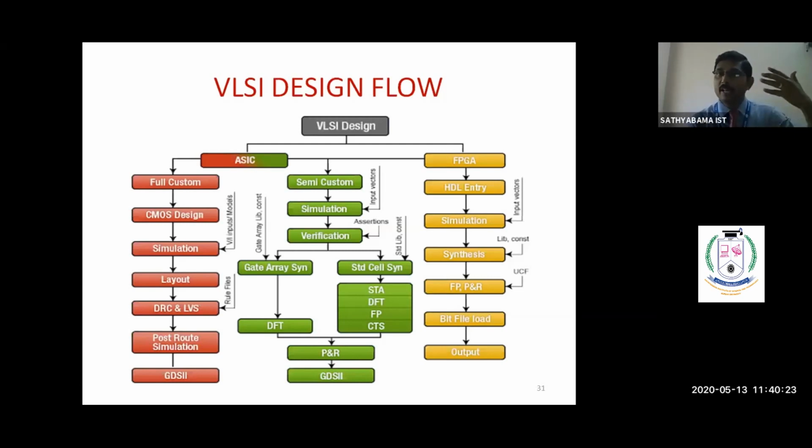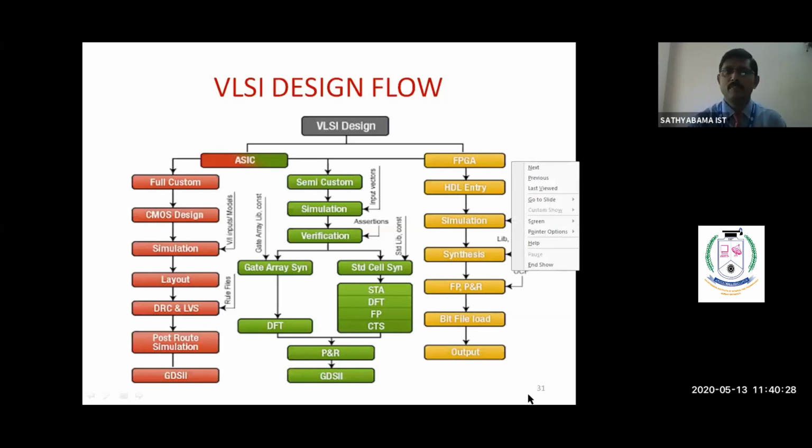So already we are making the schematic, then we are going to make the layout. You are already familiar with how to make layouts. With respect to the schematic, we are making the stick diagram. Then after the stick diagram, we are making the layout design. After making the layout, we are going to do the DRC and LVS.